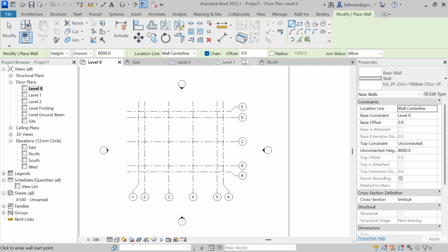Okay. So then when we select this one, external wall with this arrangement, you can see on the option bar here, you can select the height, and by default it is height. So from the bottom to up, there is another selection, depth, so it will create down depth. Then unconnected, so you can connect it up to level 1 or level 2. Normally for the architectural one, you can directly select up to level 2, something like that. Because in an architectural model we don't necessarily have beams or structural beams.